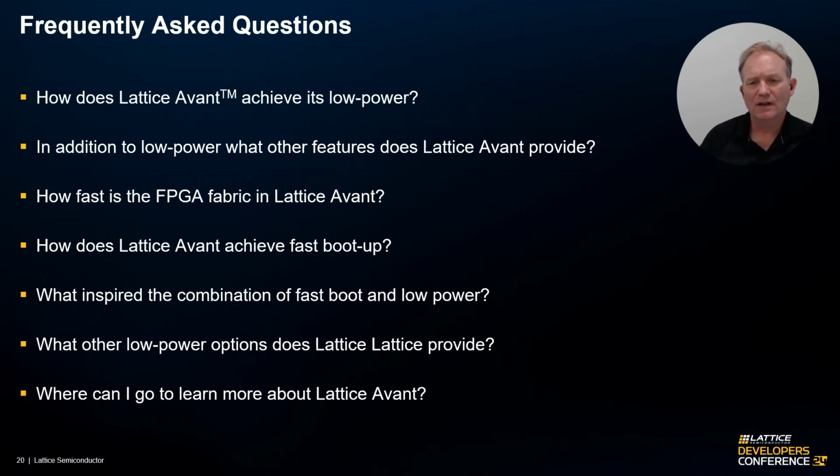For instance, the internal oscillator frequency. Is it high enough? Do we control the tolerance well enough so we don't needlessly give away performance? Do we support octal SPI or just the older SPI memories like by 1 or quad by 4 SPI memory? Have we paid attention to how quickly we start downloading from the SPI memory after power good is achieved? It's by paying attention to all of these factors and more that we're able to deliver the fast boot that we talk about.